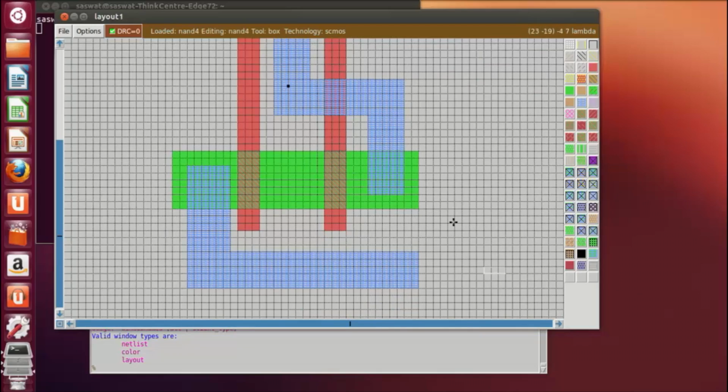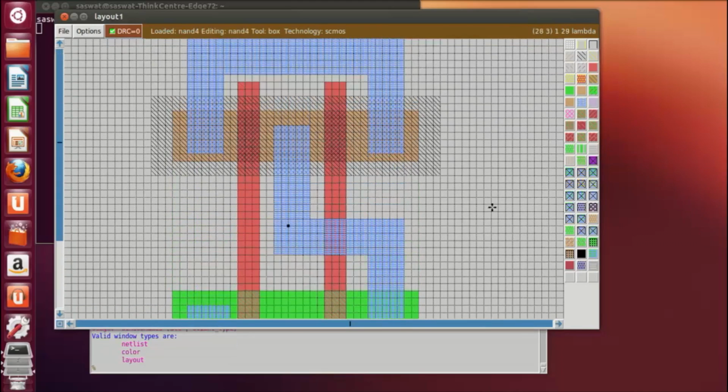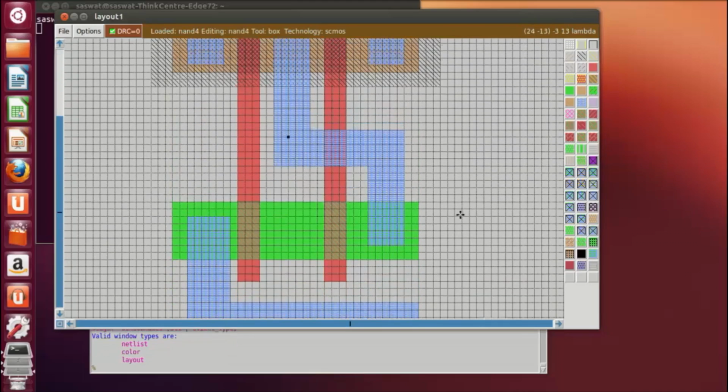So it's very easy to draw the layout, because the moment you want to select, you can select from here or you can directly select from here. If you want to remove, then just select and middle click outside of the boundary. Now roughly my layout is done.